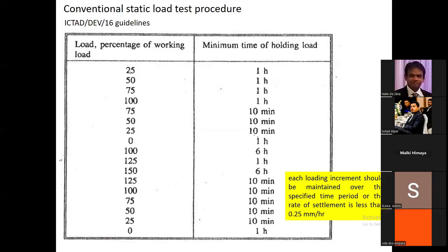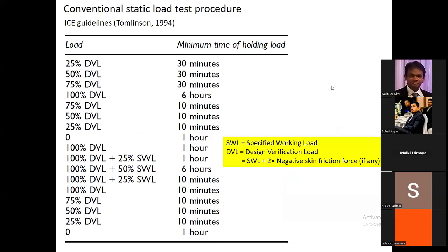And at each load, you have to hold the load for a holding time of 1 hour and so on. So different holding times are shown here. This is the loading schedule given in the CEDA guidelines, okay? It's old. I mean, the previous name is ICTAD, now it is called CEDA. So CEDA guidelines are shown here. This is the ICE UK guidelines, okay?